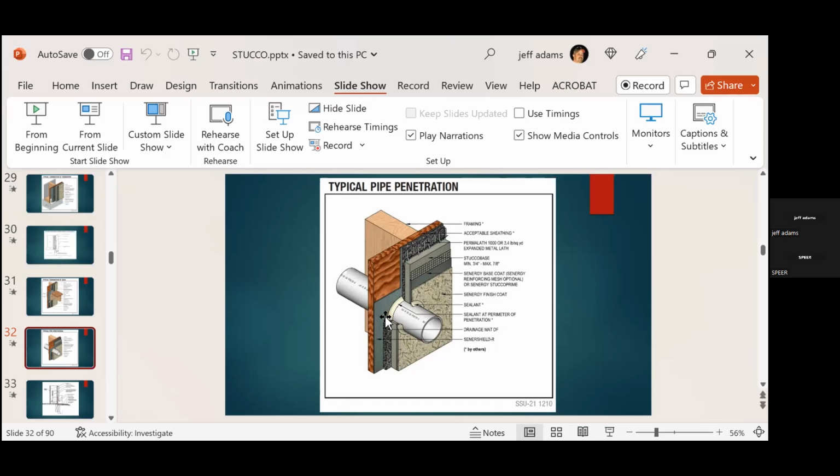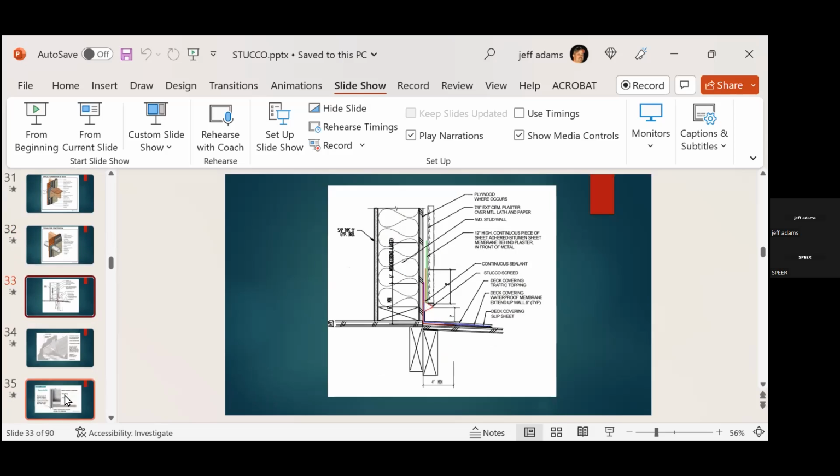You have to make all your penetrations through your WRB and flash them before you can go and put on any material. Doesn't matter what it is. Or we could be talking about cedar siding. Doesn't matter. We've got to flash our WRB. And this is a huge breakdown in the last few years. And the amount of damage that's going to be occurring to houses can be catastrophic.